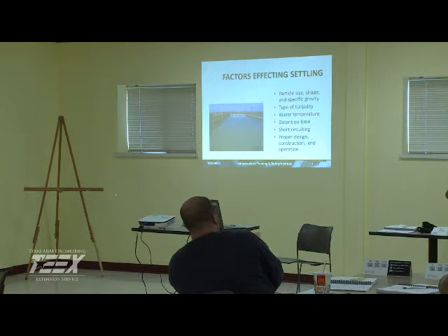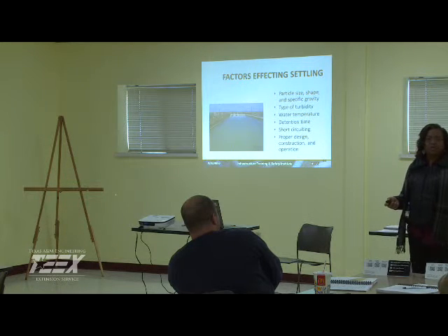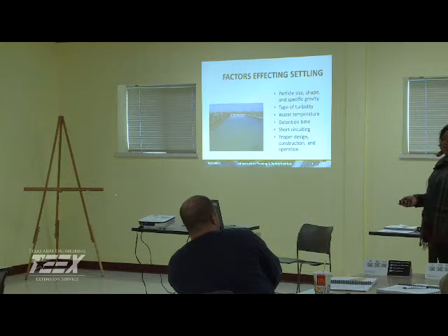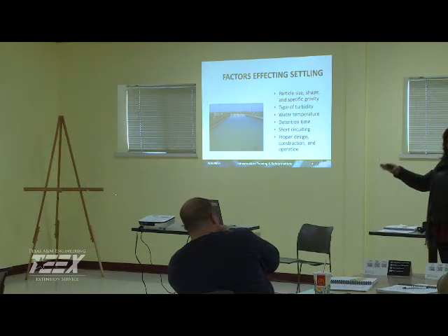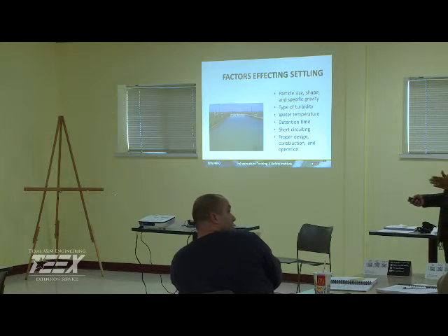Yes. And another thing that can affect the settling is poor design or poor construction of the basin to start with, which can hamper the settling process. That goes hand in hand with short circuiting. Absolutely, because a lot of times you have to get out there, maybe add baffles, and make sure your weirs are properly arranged so the flow is going the way it should.